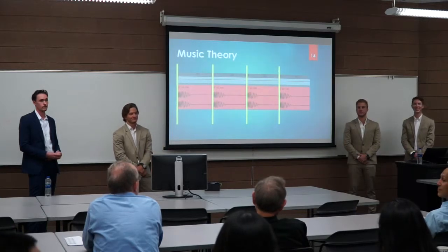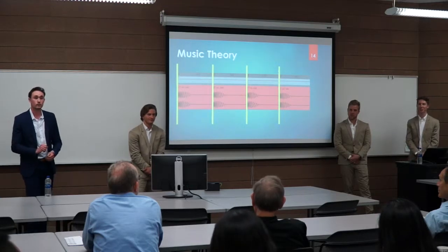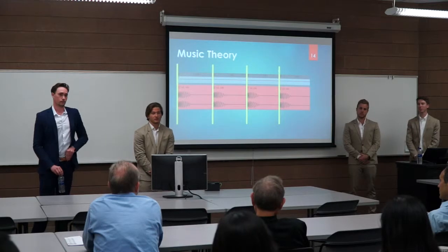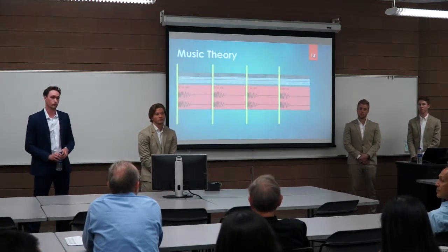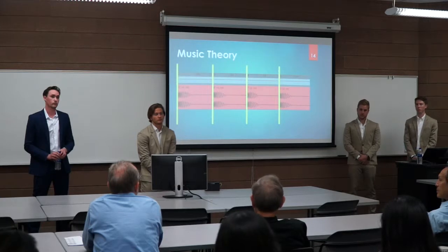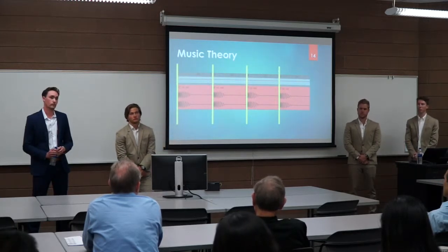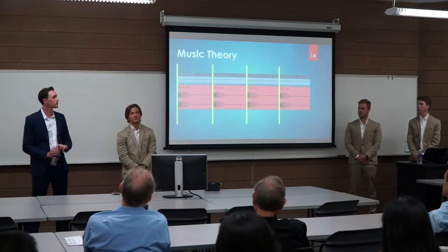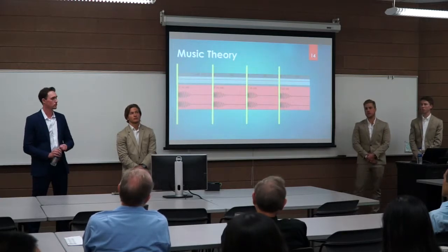So I just understood that right, the microphone you had was a digital microphone. Yes, it's I2S, which is a digital communication. Did you observe, so it obviously had A to D inside of it. Did you observe any aliasing between your software sampling and the microphone sampling? I do not think we encountered that issue.